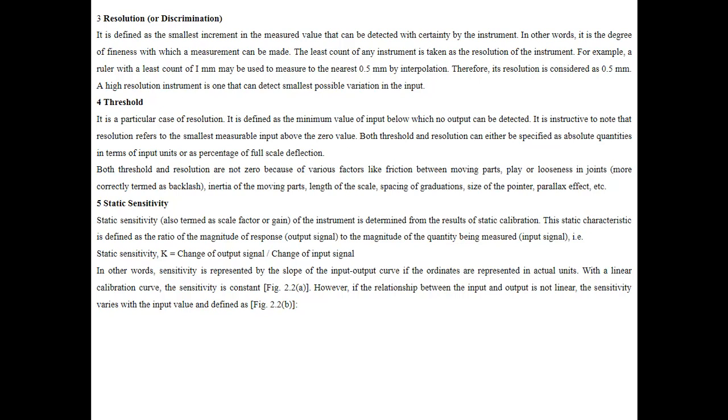Next definition is static sensitivity. Static sensitivity, also termed as scale factor or gain of the instrument, is determined from the results of static calibration. This static characteristic is defined as the ratio of the magnitude of response to the magnitude of the quantity being measured. That is, static sensitivity K is equal to change of output signal divided by change of input signal.